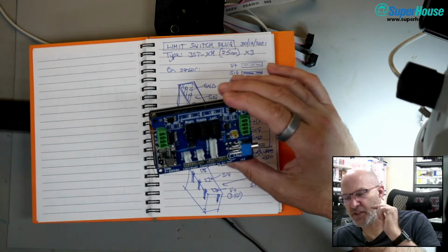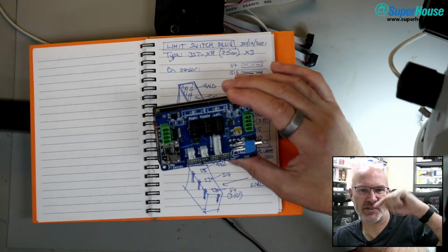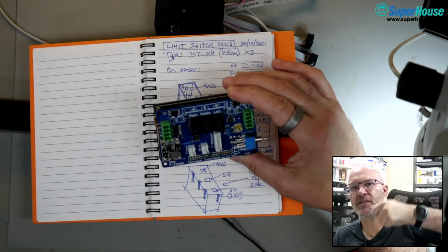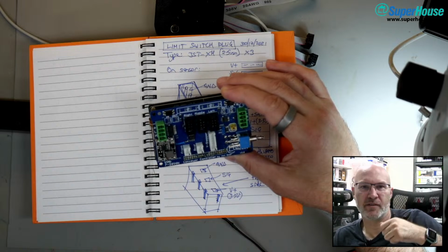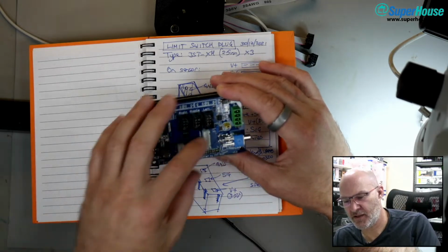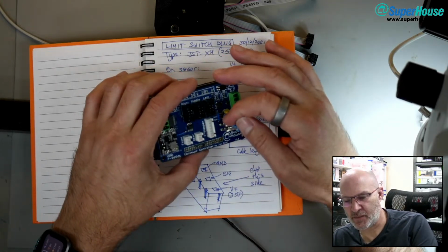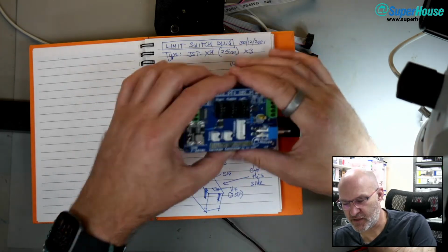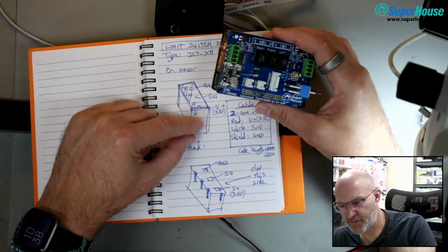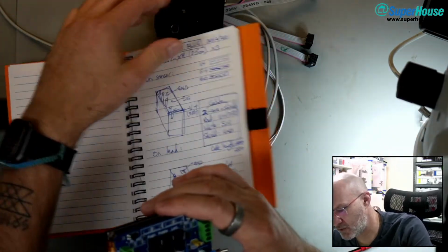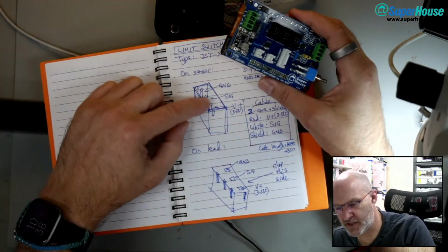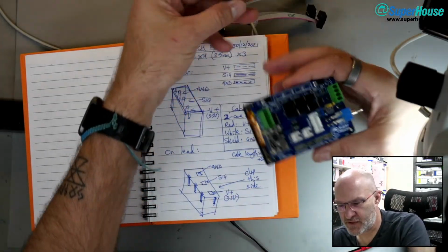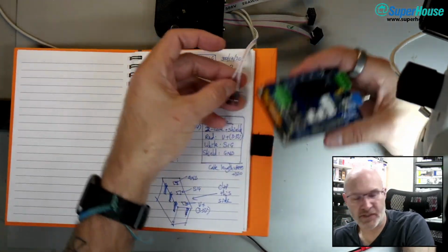With servos, they put the 3.3 volts in the middle, ground and signal on opposite ends. So if you plug a servo in backwards, it won't work, but you're not going to make any smoke come out. And I think I just followed that same logic where 3.3 volts is in the middle. But to match the connector on the actual sensor, it should be ground, signal, and then 3.3 volts. So what I have to do is make sure that I cross over 2 of these wires.